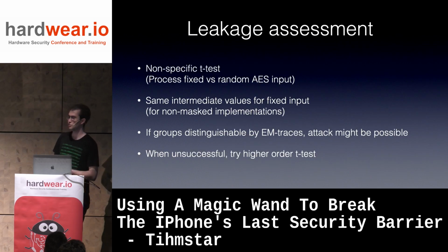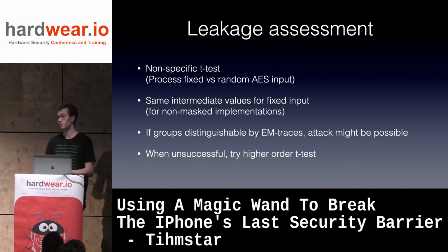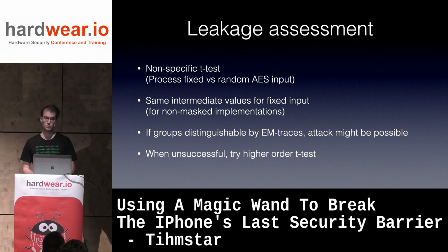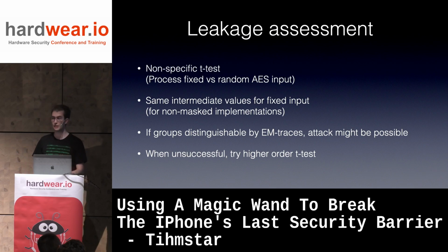After that, we can do some actual side channel analysis, which is first we do leakage assessment. So I use the non-specific t-test, basically which you feed the AES either random inputs or a fixed input, and you collect thousands of traces. So for the fixed input, you have also the same intermediate values in the internal AES state.